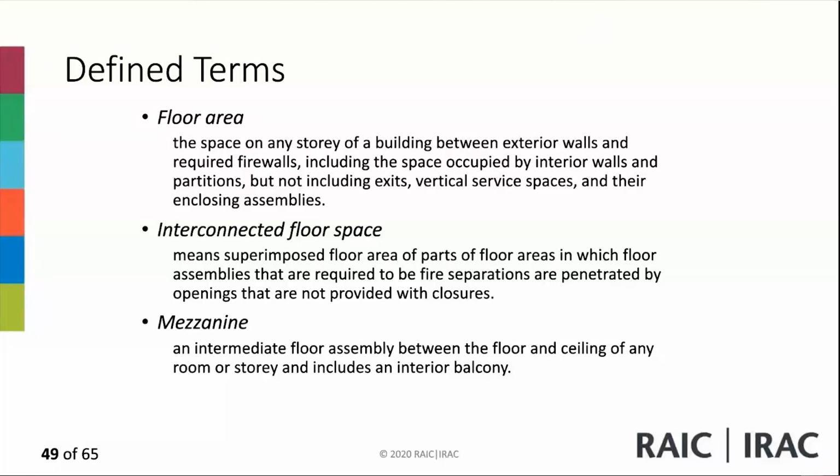So for mezzanines, except as required by sentence 5, the space above a mezzanine need not be considered a story in calculating the building height. Remember, if we have more stories, the stricter the construction requirement is. If we have fewer stories, we have more flexible construction. So that's why mezzanine determination, whether they're considered a story or not, is an important element for construction classification of the building.